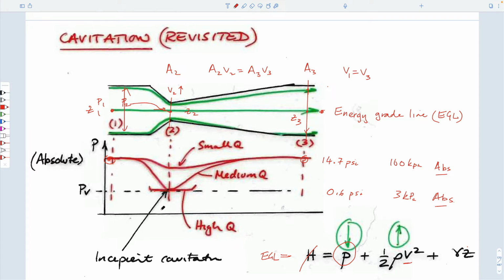So this is the reason that the turbines, the blades on deep sea submarines with nuclear weapons on them, kind of a topical subject all of a sudden, unfortunately, are big and rotate very slowly, because if they rotate very quickly, the pressures on the blades can get below the vapor pressure. If they get below the vapor pressure, they make bubbles.